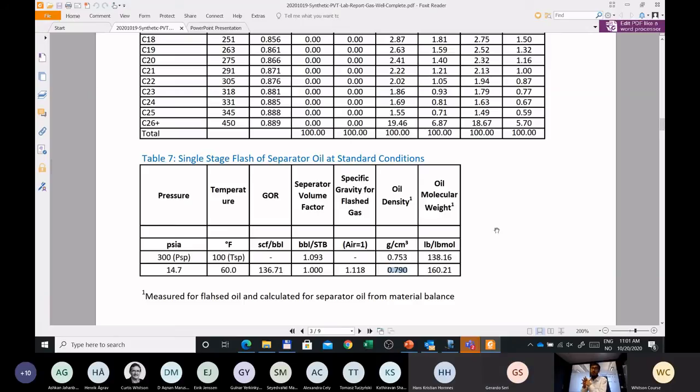So if you want to be consistent, if you have multiple samples from the field, and different samples have measured densities at different temperatures because of maybe the wax issue or something like that, then it's better that you correct all the densities to ambient condition, and there are correlations that you can use for the temperature correction, and use those corrected densities for the calculation of the Watson characterization factor, because the temperature may have a large impact on the measured density value.